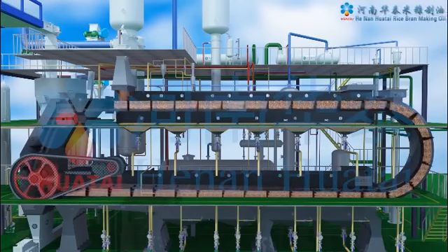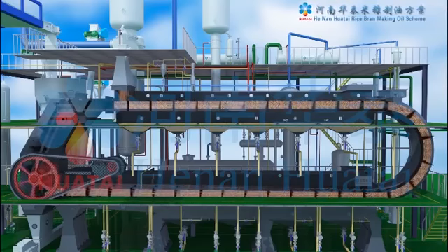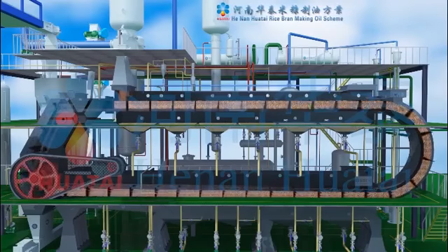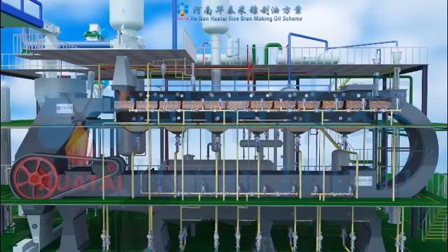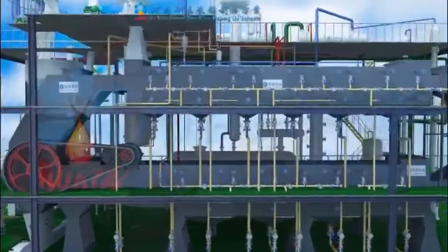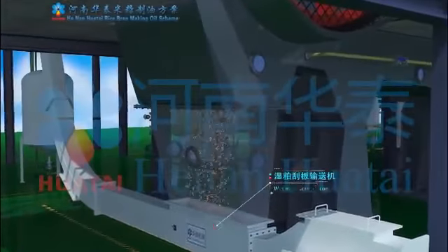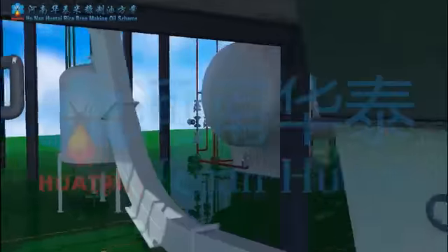The material to be extracted will be arranged in the rotor cell extractor, whose interior is designed with material level adjusting and an anti-penetration device. The material runs a full circumference and is then discharged through the outlet. The wet meal will be elevated into the wet meal sealed screw conveyor.